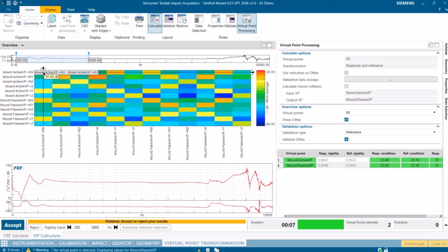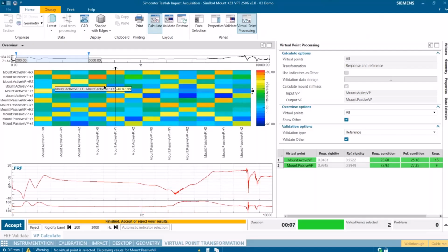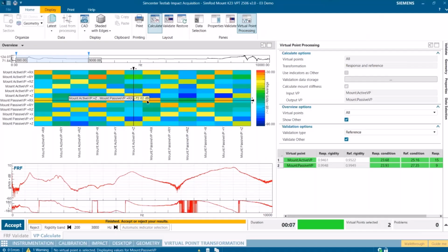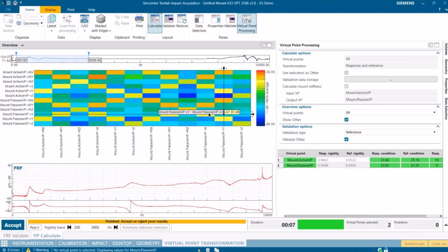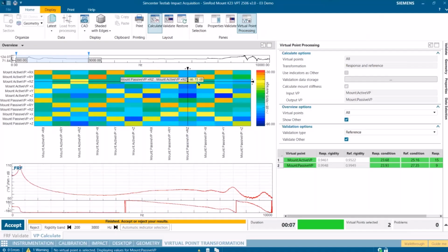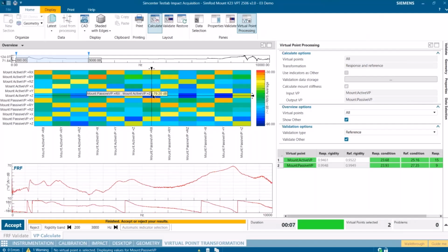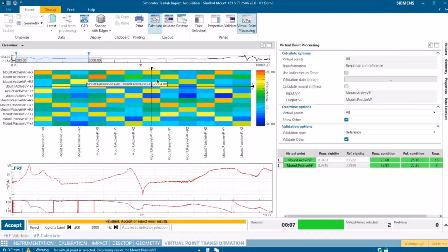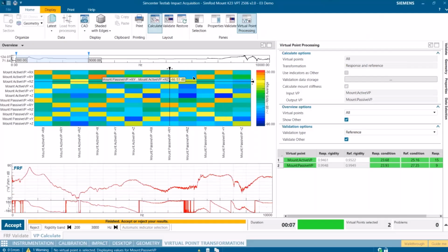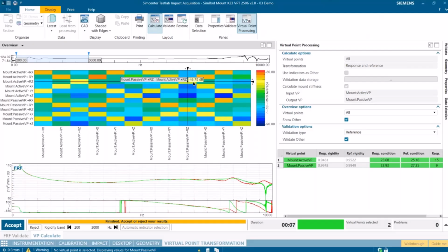The FRF matrix that we calculate is this one with these crosses that you see. So that's the typical pattern that you will find in this kind of measurement data. And the part that is interesting for us is this top right, but also the bottom left matrix, which are the off-diagonal parts. So this is where all the transfer properties are stored.